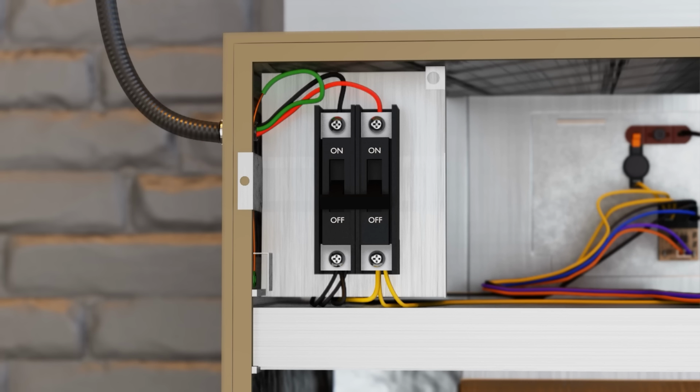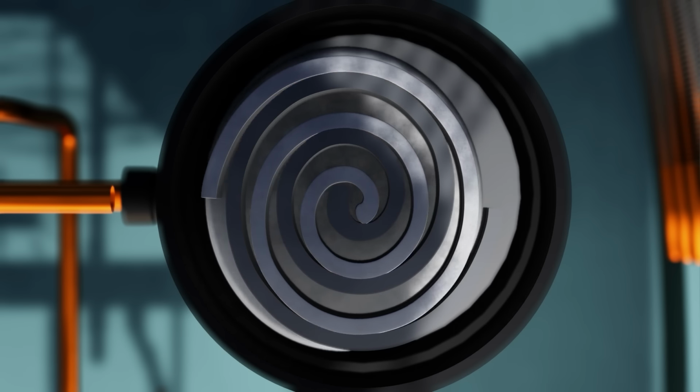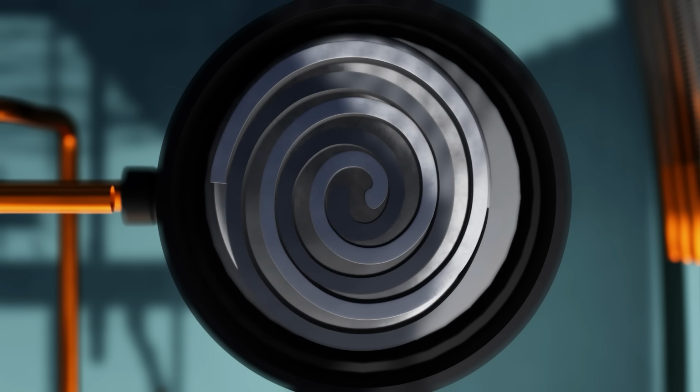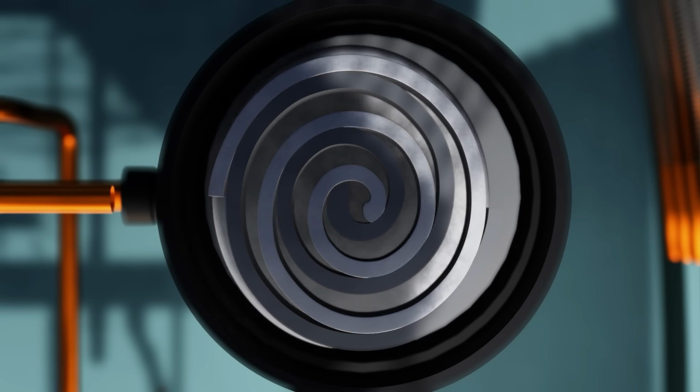The first thing I want to talk about is the compressor. In this model, we're talking about a scroll compressor. A scroll compressor uses a fixed scroll and an orbiting scroll. The fixed scroll is on top, and the orbiting scroll is driven by a motor, which then creates increasingly smaller pockets that trap the refrigerant and pressurize it and create the pressure differential to get the refrigerant moving through the system. The refrigerant is the medium that we use to move heat around by compressing it and then expanding it once again, as well as a phase change.